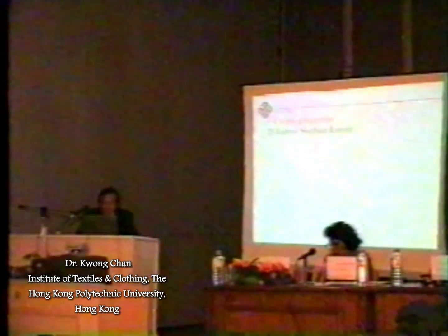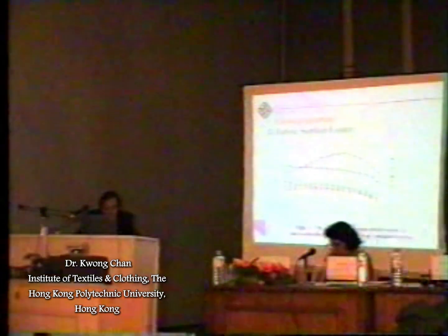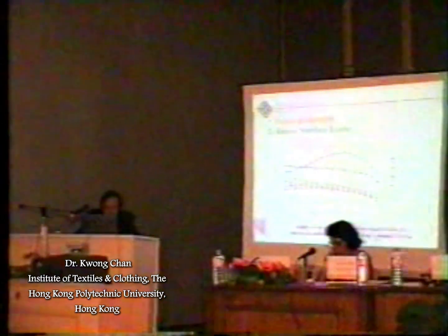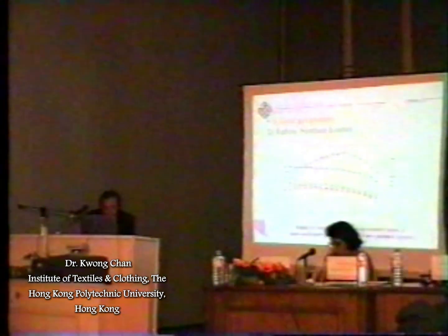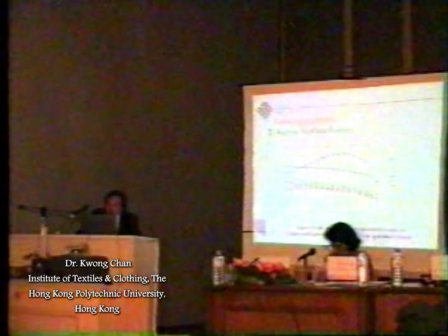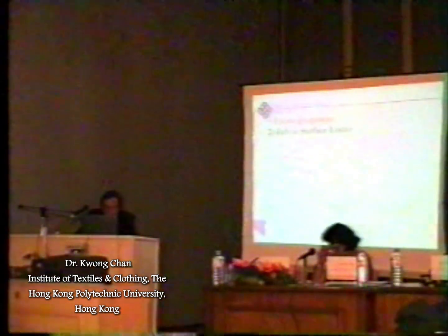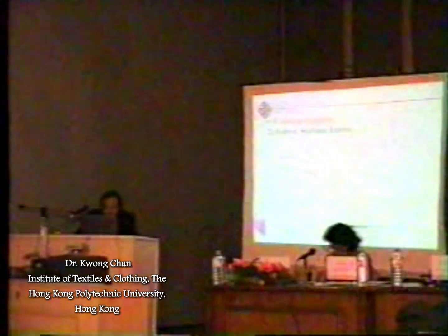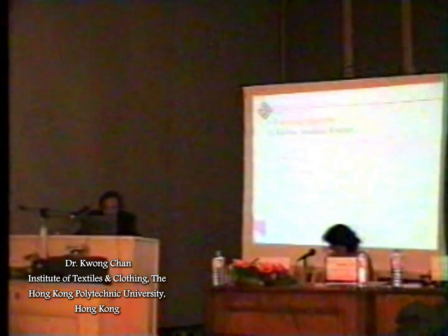Second, the fabric surface luster. The figure shows the glossiness distributions of untreated and laser-treated nylon fabrics. The blue line is the control. The laser treatment results in a decrease of the glossiness in both the weft and warp directions with an increasing number of pulses.